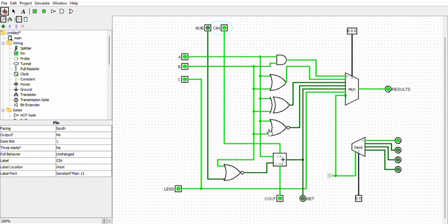So this is the multiplexer. So these are the inputs. We have inputs A and B, which accept binary data, along with control signals such as the sub, and the carry in, and the operation execution. The central part of the circuit houses the logic for performing both arithmetic calculations like addition and subtraction, aided by the XOR gate, and bitwise logical operations.